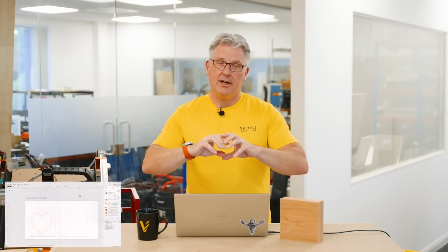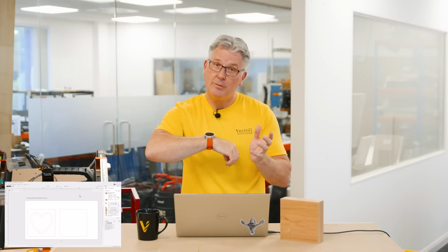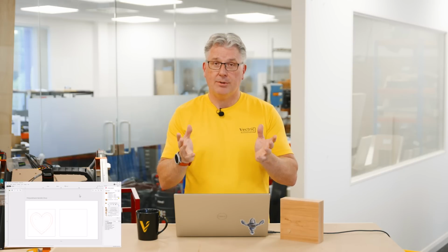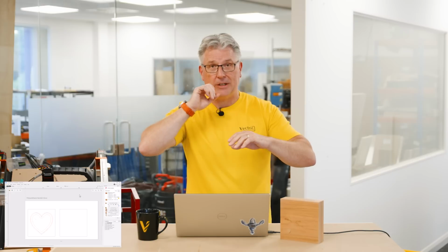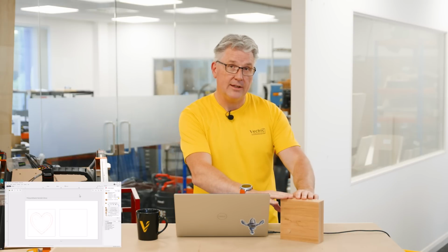So I think that worked out really quite nicely. You can see how the clearance pass got rid of a lot of the material, went in with that small ball nose, and we actually made the molding toolpath. And then we used the pocket toolpath to pocket it down, so I had that nice flat top and it was the right thickness. And then I cut out past the tabs, so everything worked out as I expected. So let's go ahead now and look at the rest of the file that I used to make this music box.